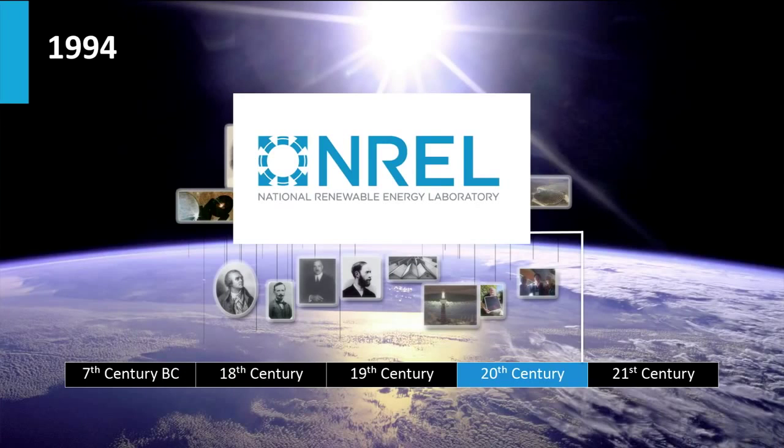In 1994, NREL in the US developed concentrator solar cells based on III-V semiconductor material. The cell, a gallium indium phosphide, gallium arsenide-based 2-terminal concentrator solar cell, exceeded the 30% conversion limit. The concentrator PV technology will be discussed in weeks 5 and 6.